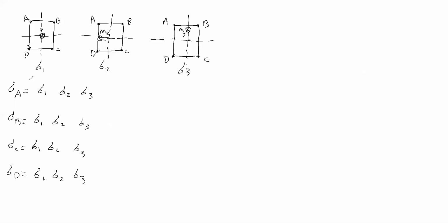So for sigma 1, we don't have any problem because this force is compression, right? Which means sigma 1 for all the cases is negative, a compression. Sigma 1 is P over A. Now I want to solve together. For A, put your thumb in the direction of MZ. Point A is compression or tension? Compression. Negative. Point B, also compression. And definitely points C and D are under tension.